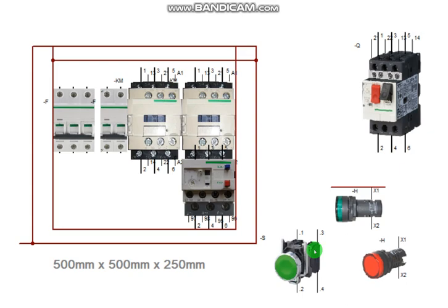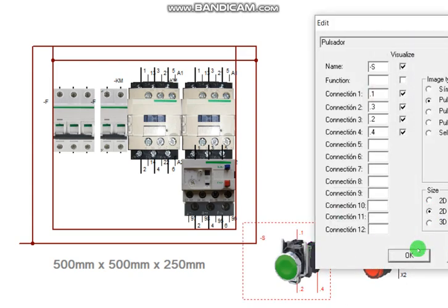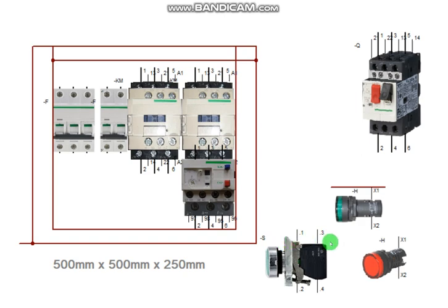Let me give you the height of this too as well. Look at the height of this. Calculate the height of this, as equally the height of this. Add it to the height of this to determine your depth and add allowance. So the depth can also be half of this. So 250 millimeter is okay. That is half of this place. So half of this place can accommodate the height of contactor and the height of your lamp. So in that case, specify 500. The new one should be maybe 600, 550 by 550 by 250. So this is the size of your panel. This is how to determine this one. This is method one, right?